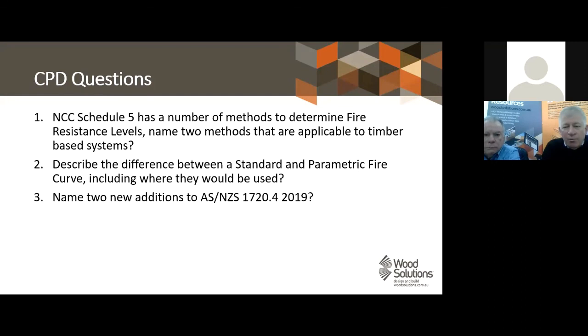Fire protected timber has certain applications of buildings that it can be used in, in the low to mid-level building range. And I always give an example for a Class 2 type building, 2 storeys. I've given up counting. Last time I found 6 or 7 different ways of meeting the fire resistance in the BCA for a 2-storey apartment building, and half of them are methods which don't require fire protected timber.